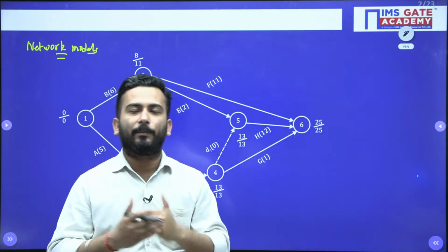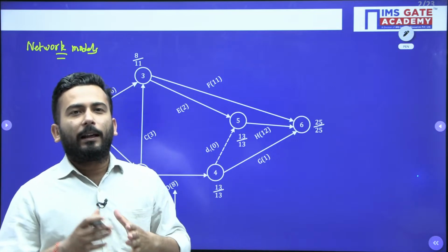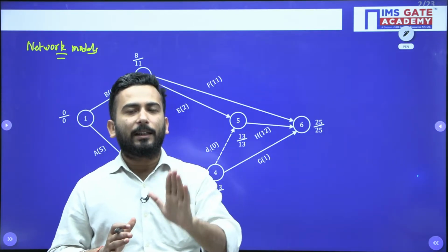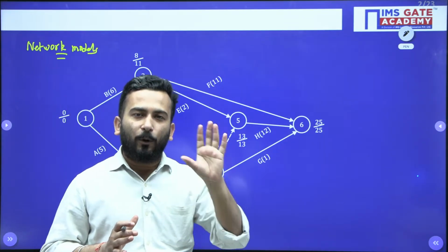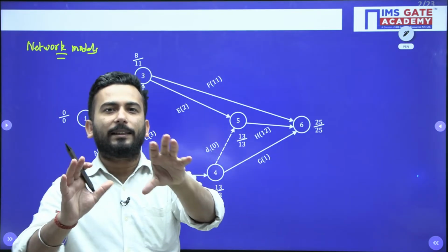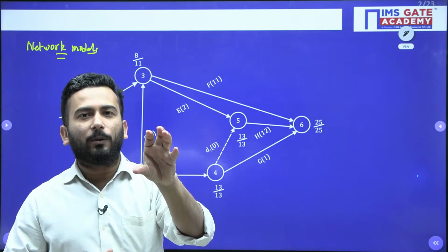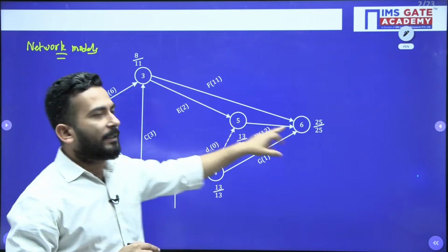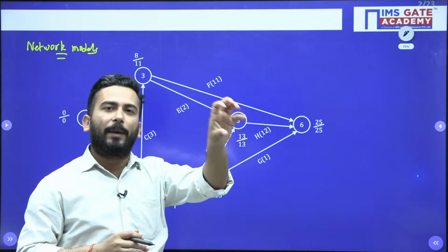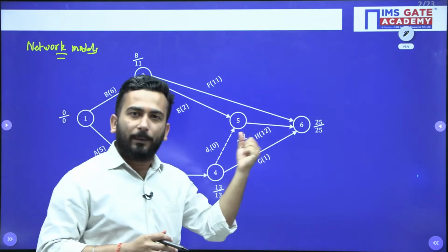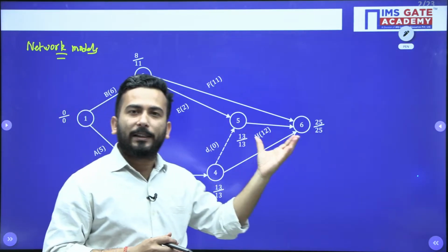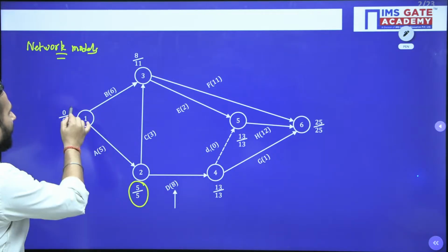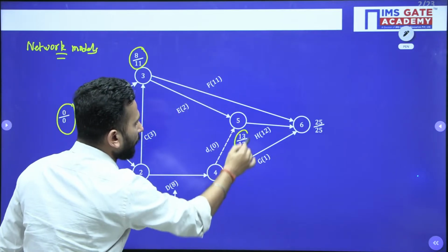See, the first thing that we do in a network diagram is calculate 2 times for any node, and that is done with the help of forward pass computation and backward pass computation. Now in forward pass computation, for reaching any node, just listen very nicely, suppose we are reaching with the help of 2 ways, we take the maximum time. So suppose there are 1, 2, 3, 4, 5, 6 nodes, whatever number of paths are there for reaching these nodes, we will be taking the maximum time, and then we have to come backwards and take the minimum time. So forward pass and backward pass. At the end of forward pass and backward pass, above each node there will be 2 times, and those 2 times are written over here.